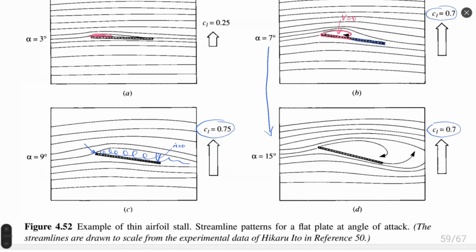And as I told you before, according to theory of aerodynamics and also compressible gas dynamics, you will see that even a wedge or small conical body would be much more performant in terms of lift creation than plate. Nobody uses plate in aerodynamics. For creation of lift. For creation of drag, yes, as we discussed last time, for creation of flow recirculation, plate is extremely efficient. It allows to decelerate airplane and has light weight.